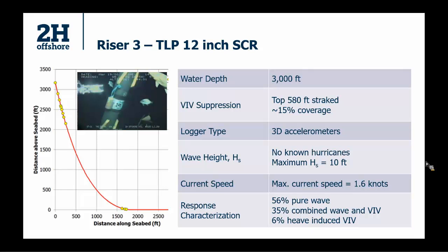When we did the response characterization, we saw that about 50% of the time it was pure wave, 35% of the time it was combined wave and VIV, and we observed this heave-induced VIV about 6% of the time. That is something that we know exists, but we typically do not use it in design. And if we observed it for a TLP, you can imagine it does exist for semis or FPSOs.